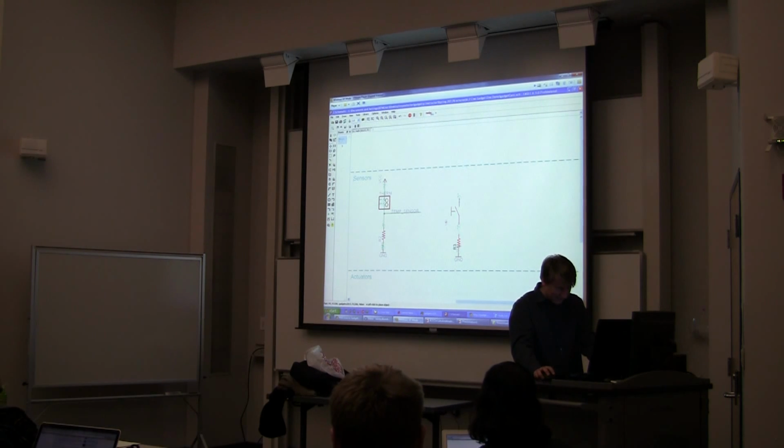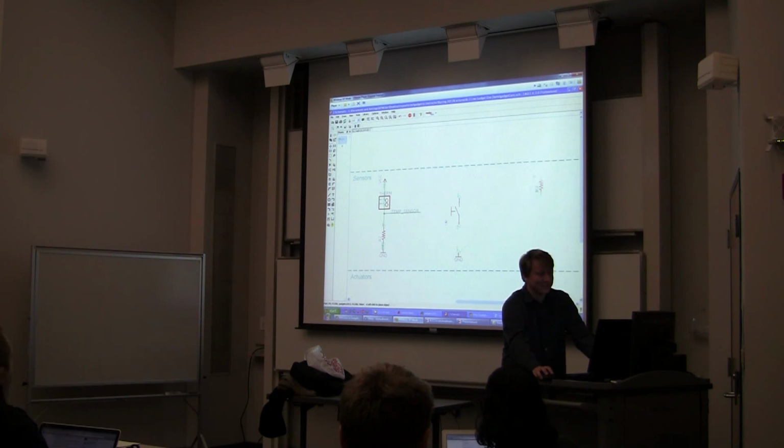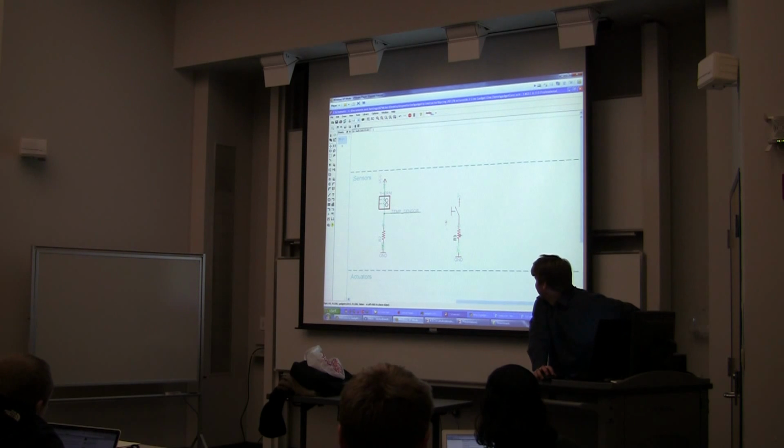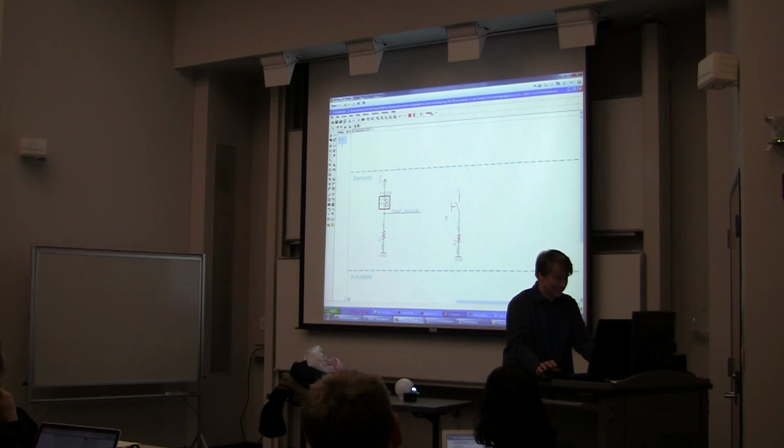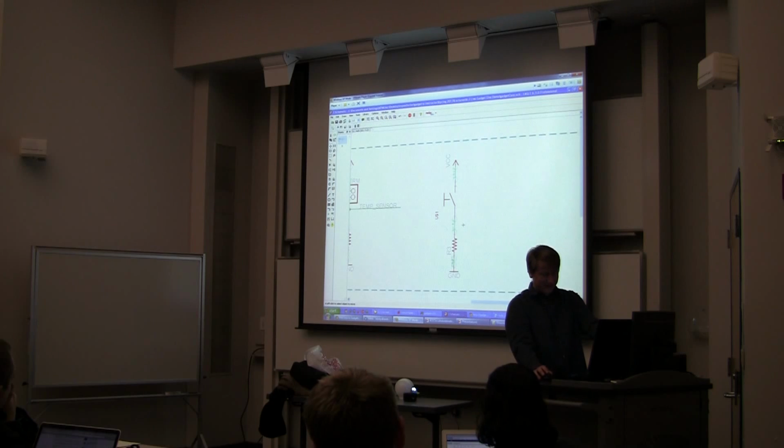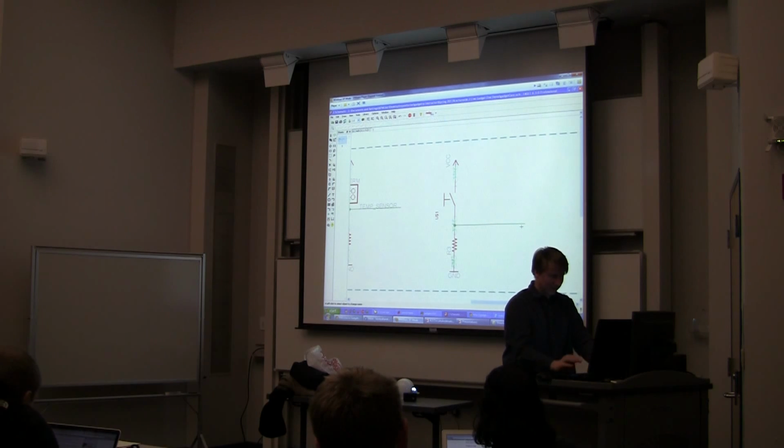Okay, I'm going to put this resistor in here. If you want to get lazy, there's another way. If you connect the two legs, it creates a net for you. And then I can create another net there. So there's another lazy way to make nets. Get tired of drawing those little nets. And I can do the same from there. So I've got my button. So when I press the button, it goes to VCC. Otherwise, it goes to ground. I just have to connect the actual net. All right. So I'm going to call this one button.